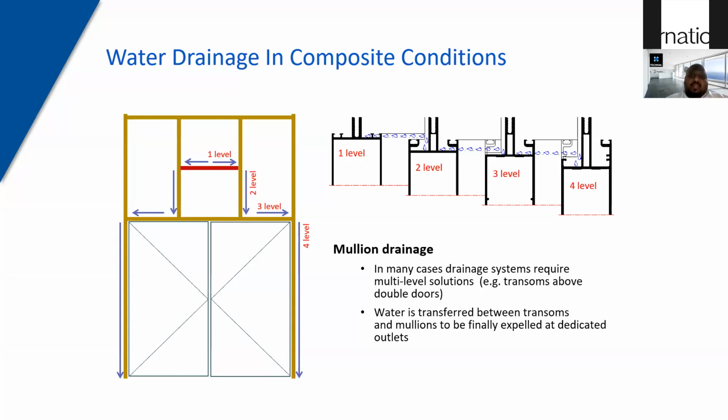So it's very important that when you choose the facade aluminum curtain wall system, you consider how the water is drained out. So always go for a pressure equalized system and ask your supplier or your installer about the strategy for water drainage. This topic is not very common in Dubai, in the Middle East, because it doesn't rain so much. But the situation is changing. As I mentioned, it's raining more than ever these days. So you don't want your building to be exposed to risks in the event of rain.